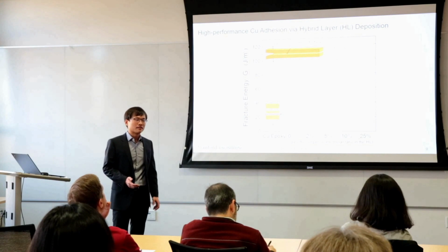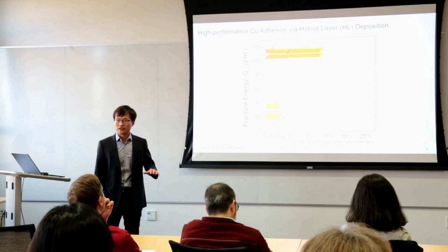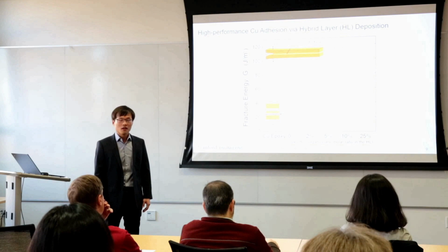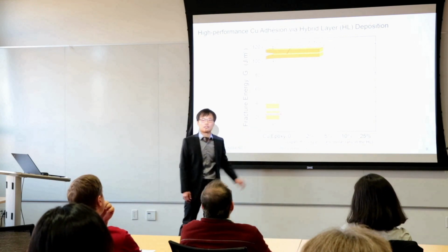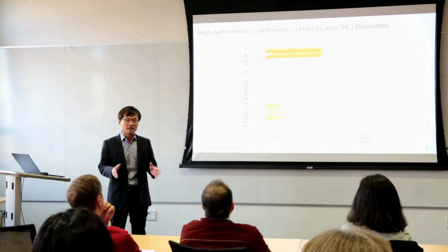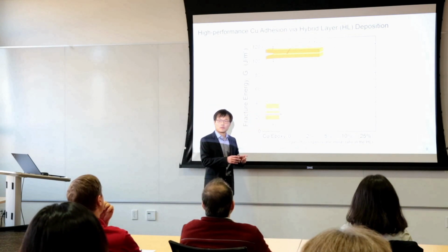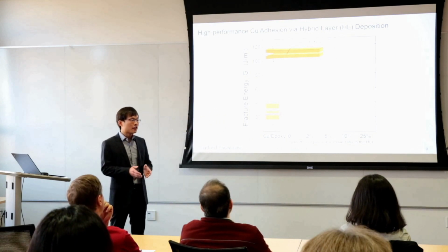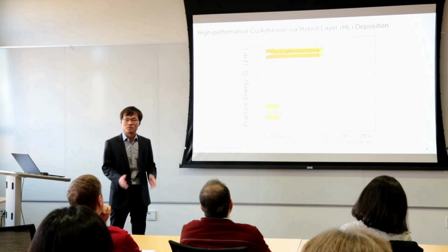The reason that we put down this hybrid layer on the copper surface is to promote adhesion on the copper surface. What kind of adhesion improvement do we get by putting down this hybrid layer? The first data point is a measure of adhesion at the copper-epoxy interface without the presence of any hybrid layer. Basically, we bond together two plain copper substrates, as shown in orange, using brittle epoxy as shown in yellow. And then we break it apart and measure adhesion. The adhesion energy measured for that case is very low, only 10 joules per meter squared.